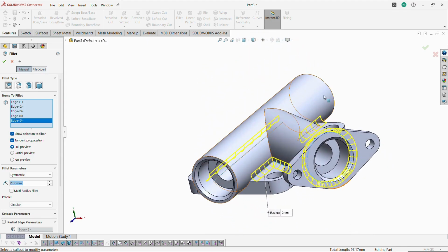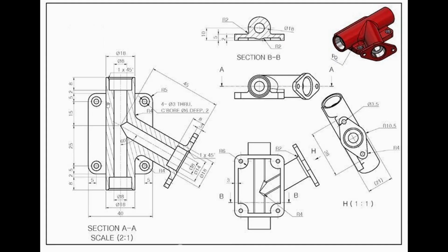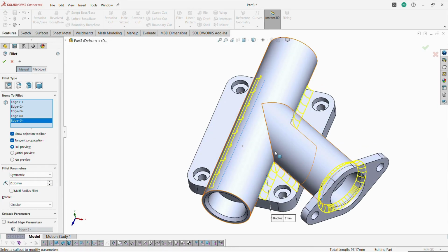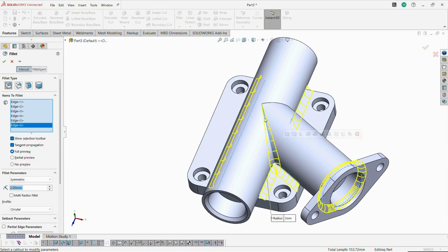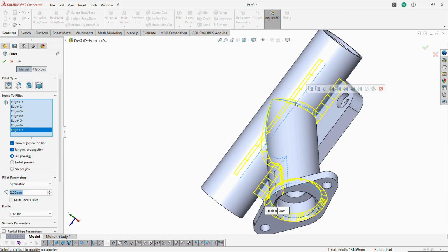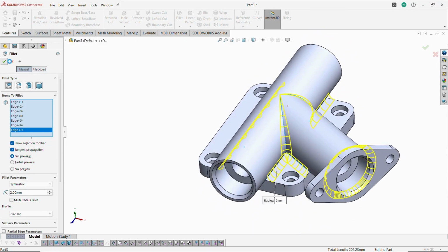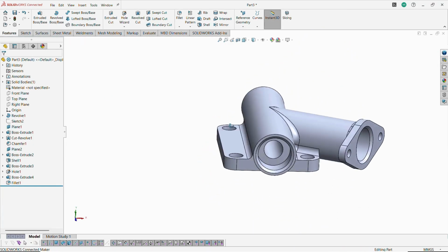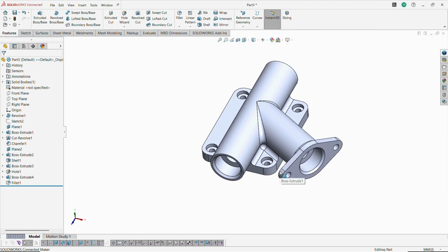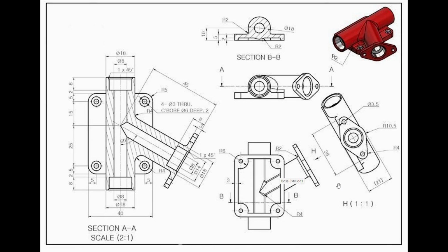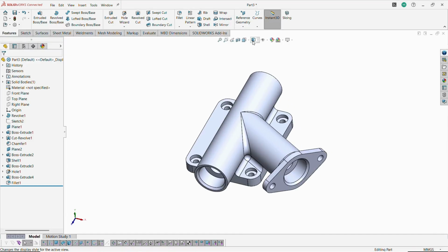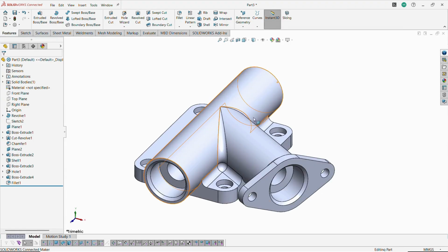Circular edge, sharp edge, as well as this arc type of edge area, that is a merging area. Once the fillet is formed, almost the entire solid body is completed. This is how it is simply completed by using different profiles, forming a solid body at all portions, then creating a body using extruded boss features and hole wizards.